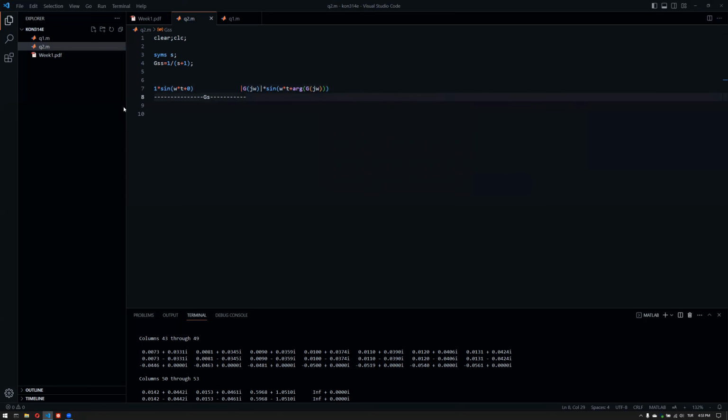This is quite nice because we can look at the Bode graph and read some values out of it for a certain frequency, and conclude things about that specific frequency. We can say that it will be amplified or attenuated with a certain ratio, which will be the gain, or the amplitude. And then we can also say that it will be shifted by this amount of phase value. So it's nice to understand how the system behaves for each individual frequency for a given Bode graph or Bode plot.